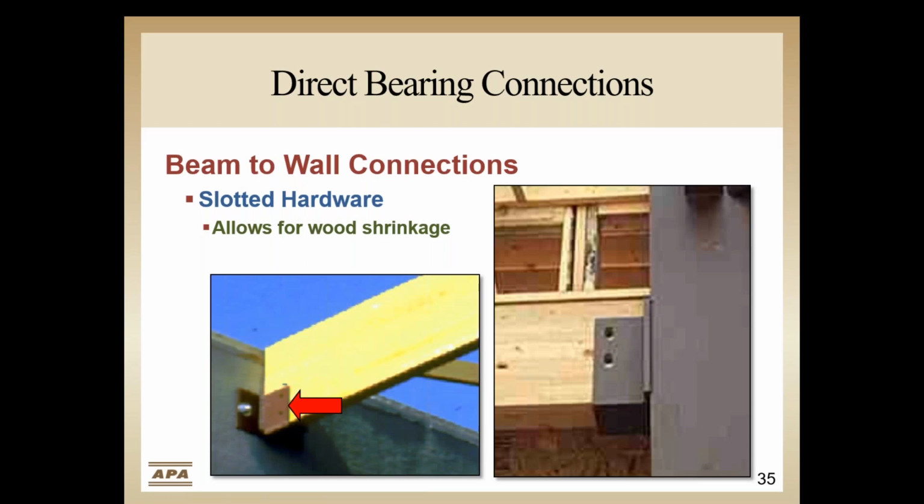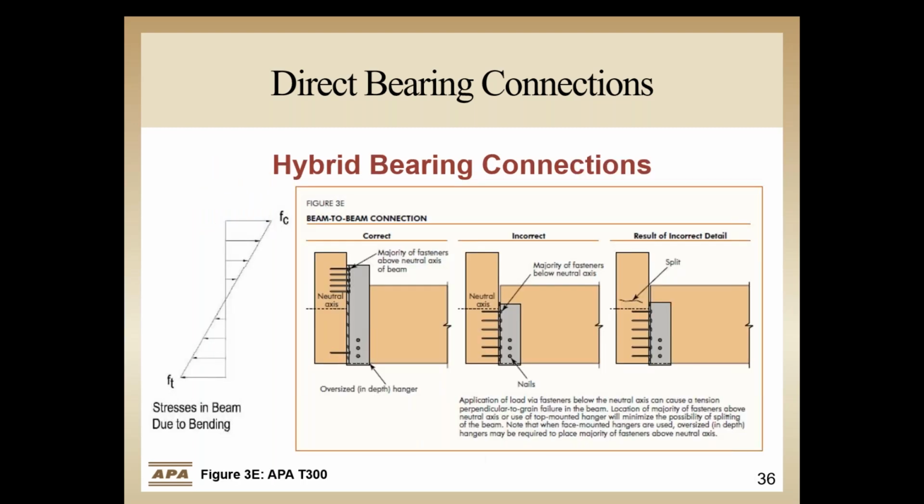These are some good details that work in that they don't notch the beam, and these connectors also provide the ability for the wood member to move in the hanger, as slotted hardware or bolts are allowed to permit dimensional changes of the wood without restriction.